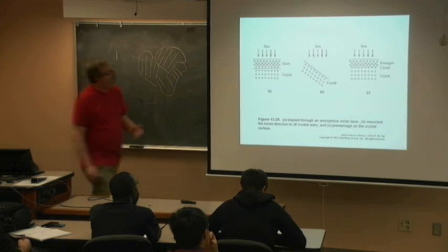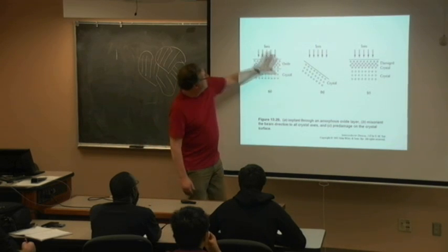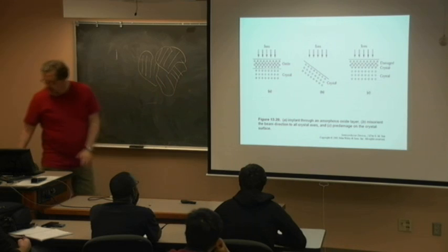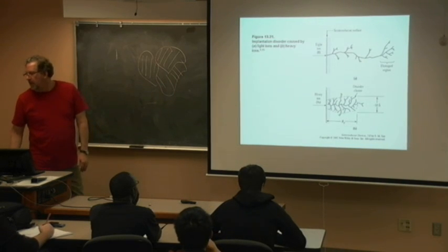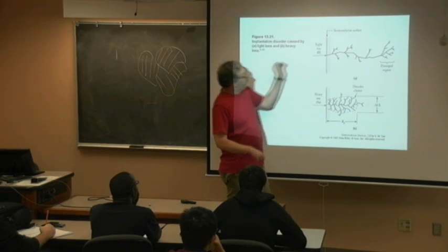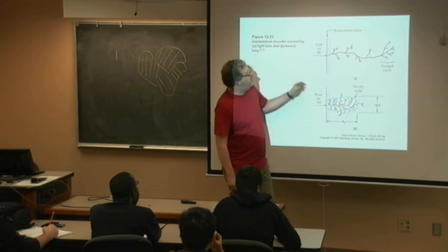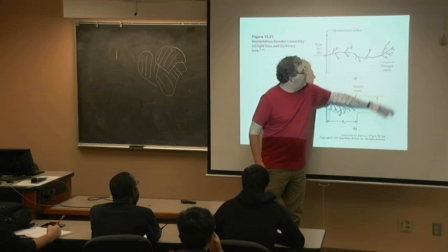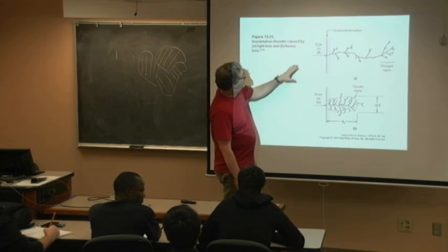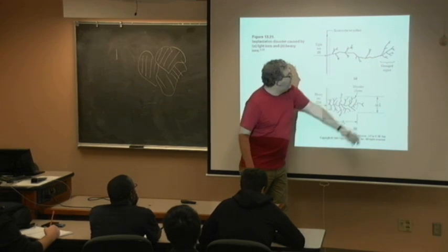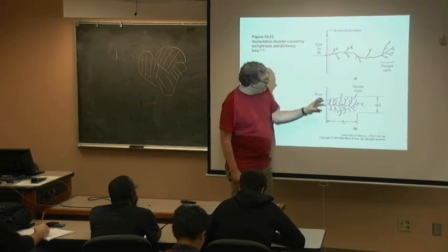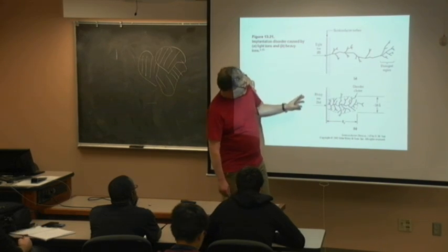And so, depending upon the crystallography and the incidence of the ions, you can marry up the angles if you know the crystallography, and you get different effects. High energy ions are going to come in, and it's going to create this whole collateral damage, where it's just going to continue to ricochet on down the line and cause all kinds of damage. And that's a light ion. It's going to come down and plant itself very deeply. A heavy one's going to come in and create a lot of surface damage, but not go very deeply.